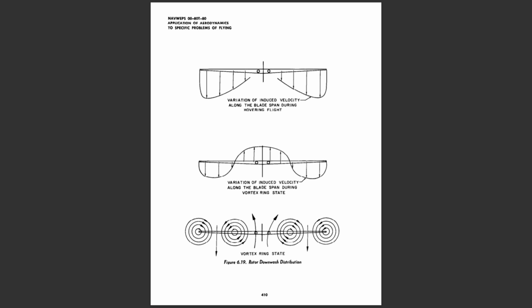There is an area of positive thrust in the outer portion of the rotor as a result of the mass of air accelerated downward, and an area of negative thrust at the center of the rotor as a result of the mass of air flowing upward. The rotor is stalled only near the hub, but no important effect is contributed because of the low local velocities. Operation in the vortex ring state is a transient condition, and the helicopter will seek equilibrium by descending.